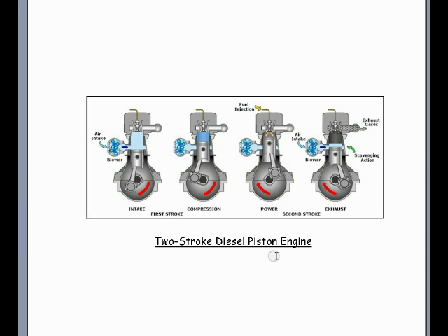A two-stroke diesel piston engine can reach very high brake horsepower, torque, and RPM all at the same time due to the fact that there is a power stroke per 1 revolution. In terms of lubrication, the two-stroke diesel piston engine could use its own separate oil supply or could tap off some of the diesel fuel in the fuel tank, mechanically pumped into the crankcase in order to support lubrication of the piston rings, piston, crank, and connecting rod.